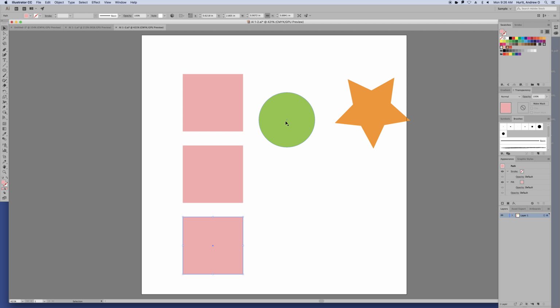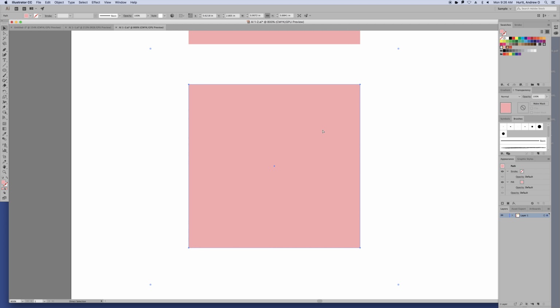As you hover over as well, especially getting used to working with Illustrator, and as we get used to working with objects, you can see as you start to hover over, I'll use the direct selection tool so it's a little bit less cluttered. You can see it'll tell you where your anchor is, so you know you're selecting an anchor point if you wanted to just use this anchor to modify the shape, or if you wanted to grab the path, which moves both anchor points.